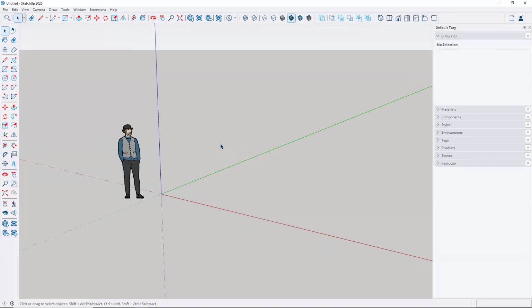There are also keyboard shortcuts, and SketchUp does provide a list of those, but I will show them to you on the screen here as well when I start using them. And I will use the toolbars over here, but you'll also see me just call out, for example, line. I know the keyboard shortcut for that is L. So I just type L and I get going, drawing lines. And then I'll tap the space bar to make that go away. So just like with AutoCAD, where you have the command aliases, shortcuts, the same thing here with SketchUp for most of the tools. Not all of them, but majority of them, the common ones.